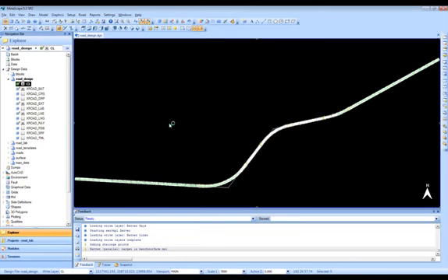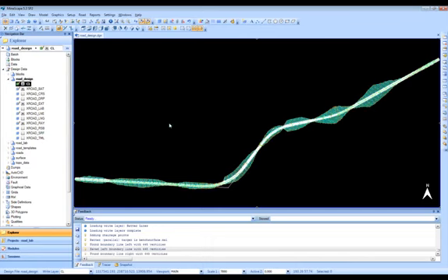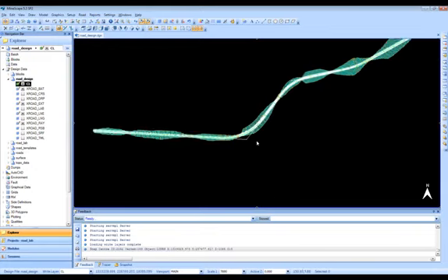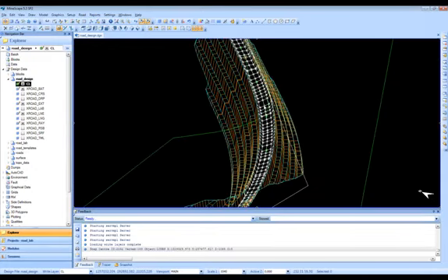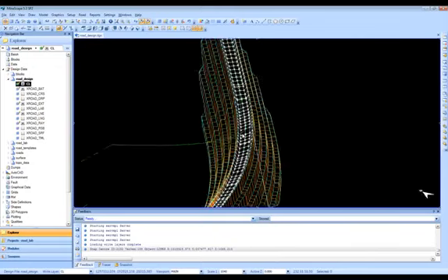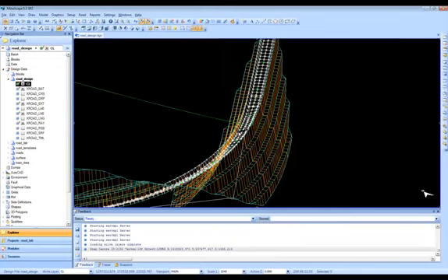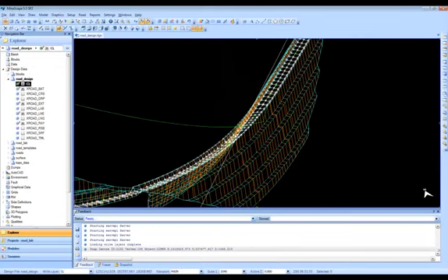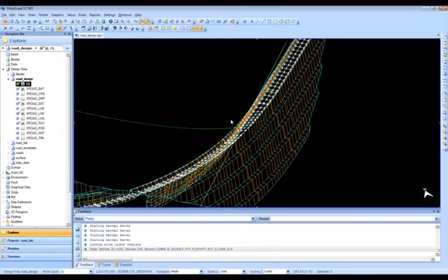So it's going to go along this road, and based on my parameters, project this road up and down through to topography, putting in those benches as I requested along both the left and right hand side of the road. And here you can kind of get an idea of those projections, and in this case benches that I've included in my design.